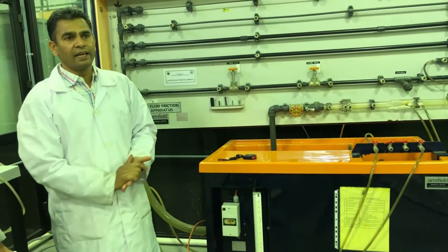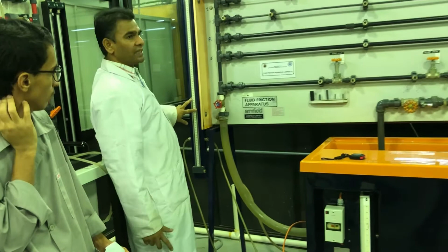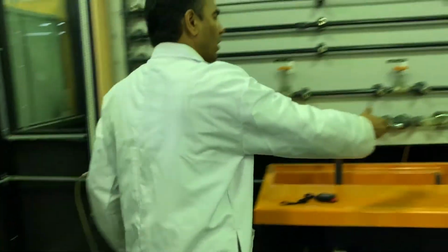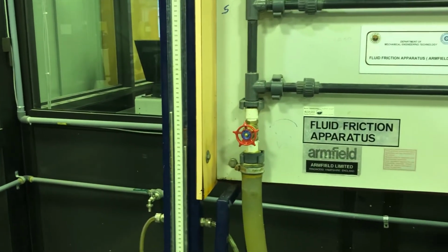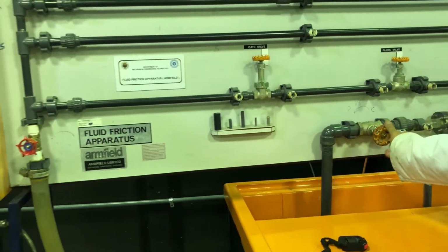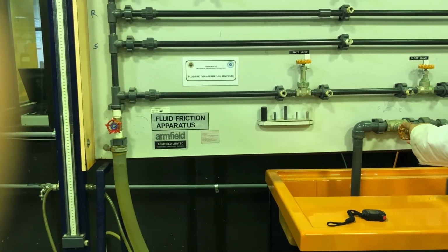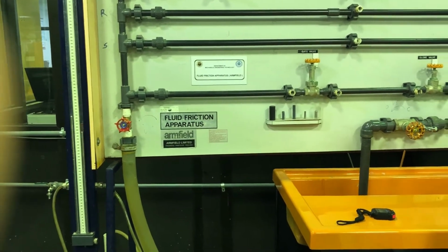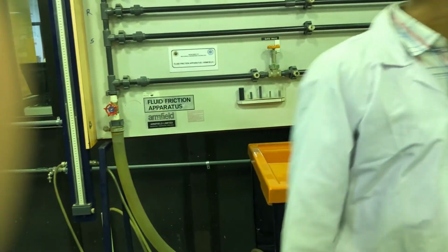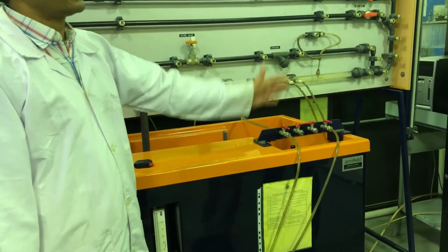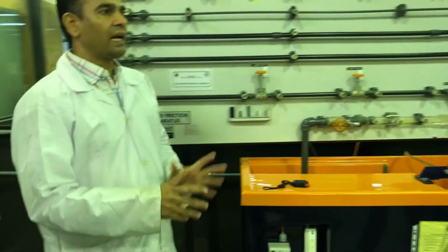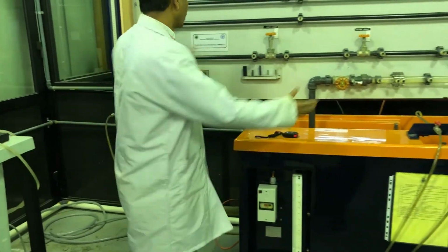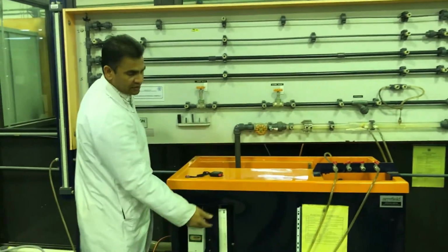Okay. Now second readings. Look at this scale and close the valve a little. How much little? So there is a deflection, there is a change in the height. Yes, there is a little change. Okay. Now I will record H1, H2 and time for 10 liter. It goes on, continue for 3-4 readings, and at last close this valve together and stop the machine.